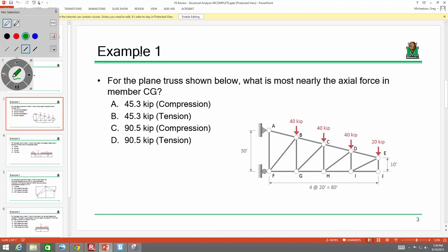Okay? Now, if you do enough truss analysis and get familiar with that behavior, you can recognize that because the diagonals are facing this way, they're going to be in compression. If the diagonals inside were going the other way, they would be in tension. It just comes from doing enough truss analysis that you start to see the patterns. But the easy ones to see are the top and bottom members.